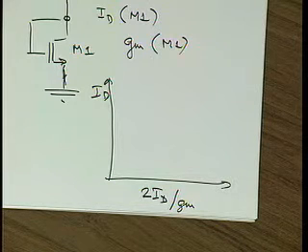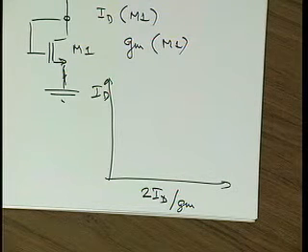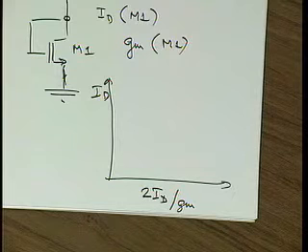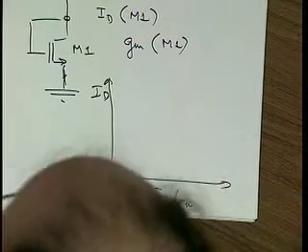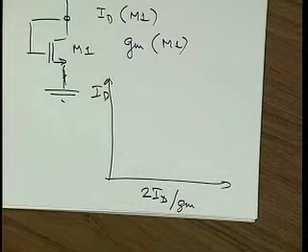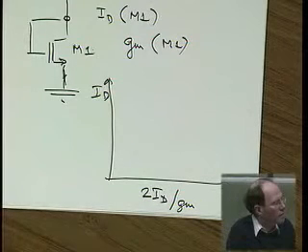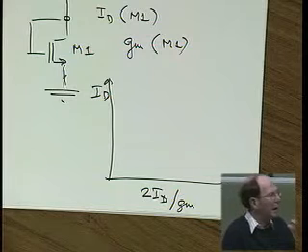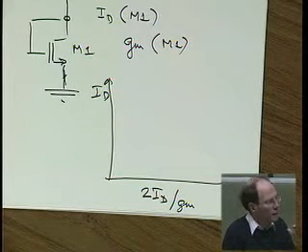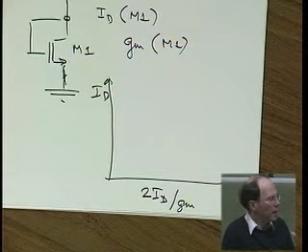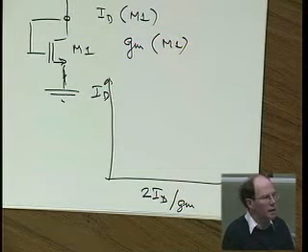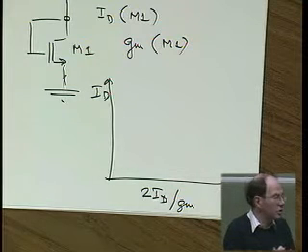You draw the ro versus the VDS, and you have three curves: one slow, normal, and fast. These are these different parameter files. When you download the SPICE text from the website, you will see that every transistor really has 3 incarnations.